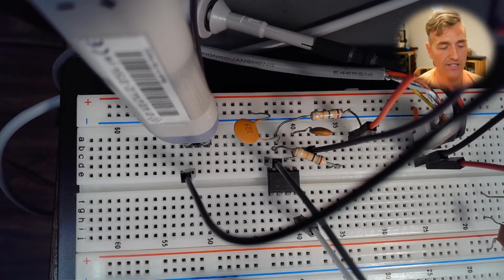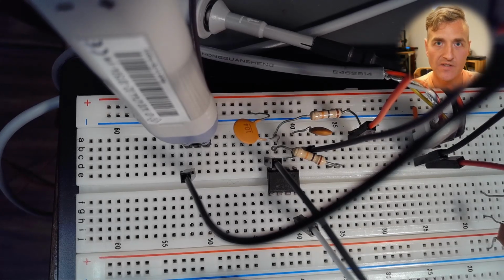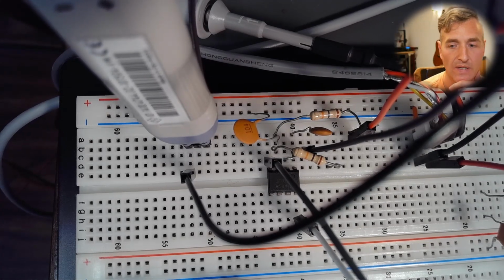But what is frustrating me is that I expected a steeper roll-off from the second order filter. I expected 40 dB per decade. And from 1,000 hertz to 10,000 hertz, it is following the first order frequency characteristics. Now, one other thing that I might do is staggered resistors.